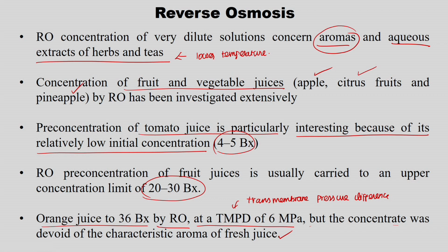So, we can go for higher temperature and higher concentrations, but what restricts me from going for higher concentration is the osmotic pressure and the viscosity of the product. If we process at higher temperature, I feel that is microbiologically safe. But we also look into what happens to the characteristic aroma of the food product, right. The more and more temperature you go, the aroma will decrease. So, that is the reason I choose RO, right.